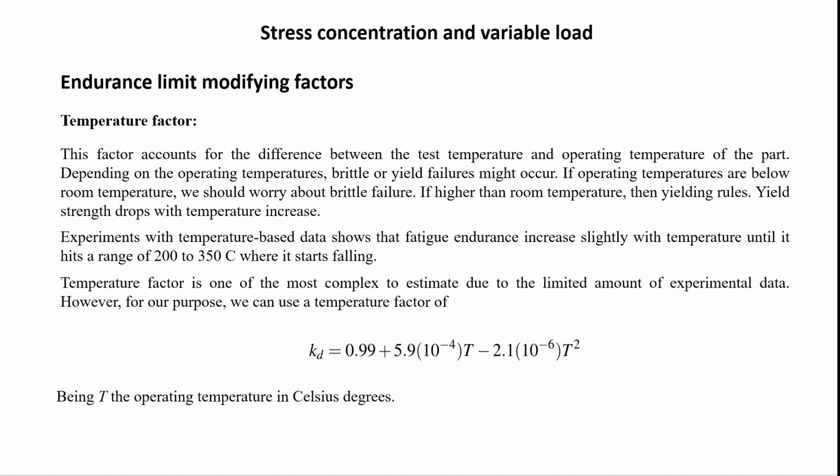Temperature factor. Temperature presents an interesting response in fatigue. So you can calculate it something like this. You can use this formula. No issues. You can go away and say, well, what's the temperature we are going to be working with in our design, and input it here, and that's going to give you the modifying factor according to temperature.